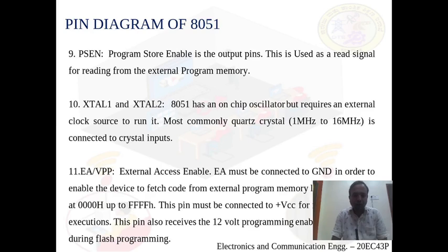And another two pins, XTAL1 and XTAL2 pins. The 8051 microcontroller has an internal, that is on chip, oscillator, but for this oscillator to function we need an external clock source. The external clock source mainly used is quartz crystal, which is connected to the XTAL1 and XTAL2 pins. These pins are input pins.